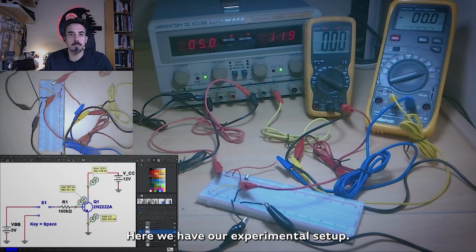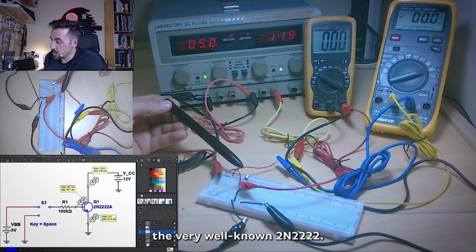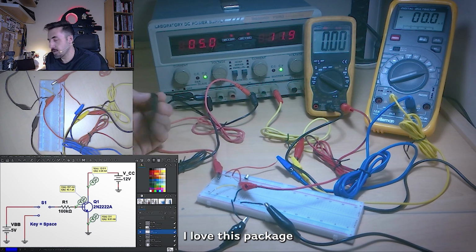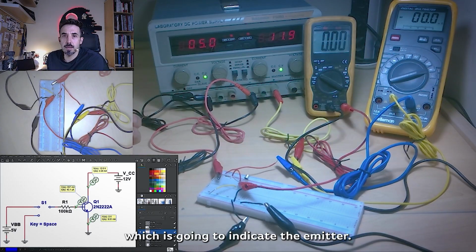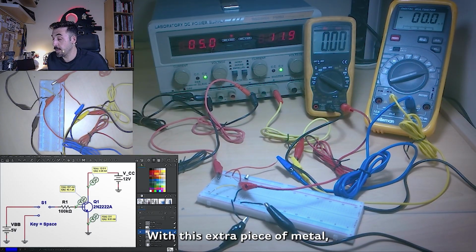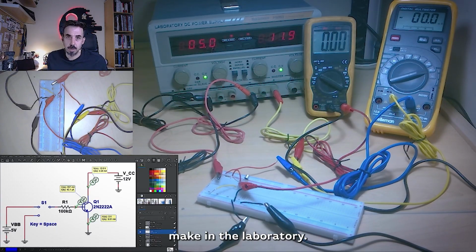Here we have our experimental setup. As a transistor, I'm using the very well-known 2N2222 with a package that is a metallic one. By the way, I love this package because you have an extra piece of metal in this corner, which is going to indicate the emitter. In the middle, you have the base and then the collector. With this extra piece of metal, it's impossible to switch collector by emitter. That is the typical mistake that many beginners make in the laboratory.